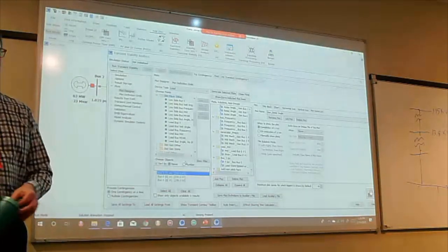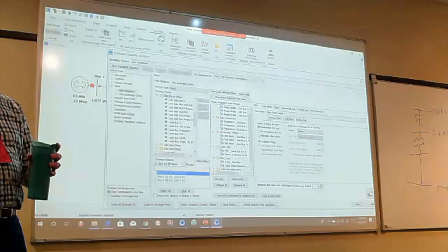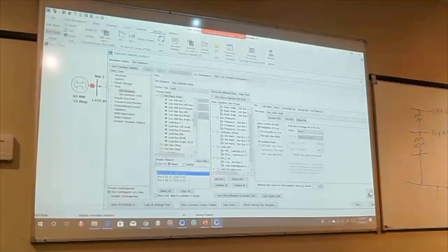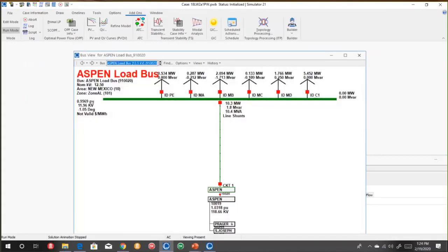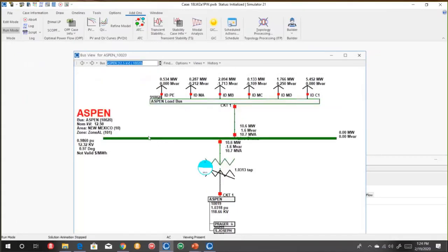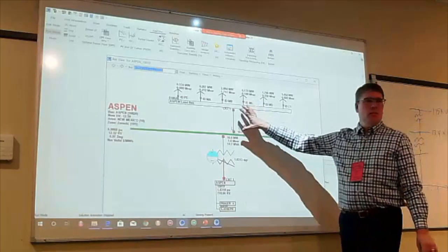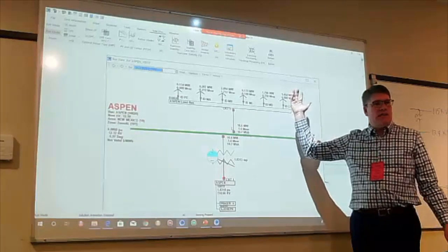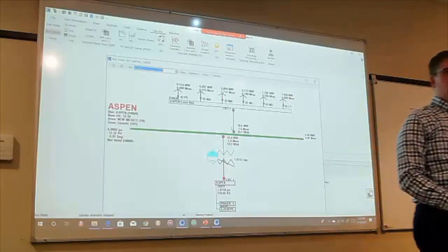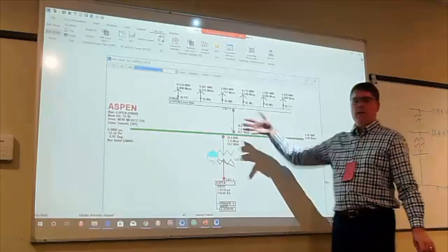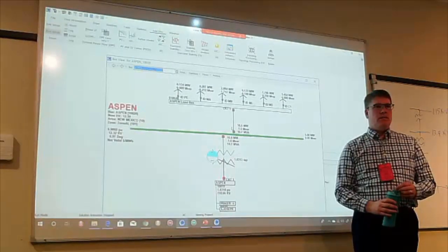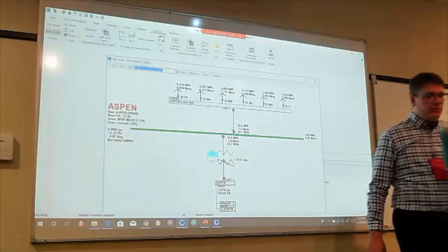What do you assume when you convert it? What's the assumption when you convert it and you look at the load bus current there? Not sure. We have to pick something. Right. So 12 and a half. We did 12 and a half, but that's what it was here. So I'd have to go look at what the transformer is. When you add one. Yeah. And the answer is, when you're done, if you don't like what we picked, you just go change it. You can just change the nominal kV of a bus, and it doesn't affect anything. Your currents will all change, but internally we're calculating everything in per unit, so it doesn't matter. All right.